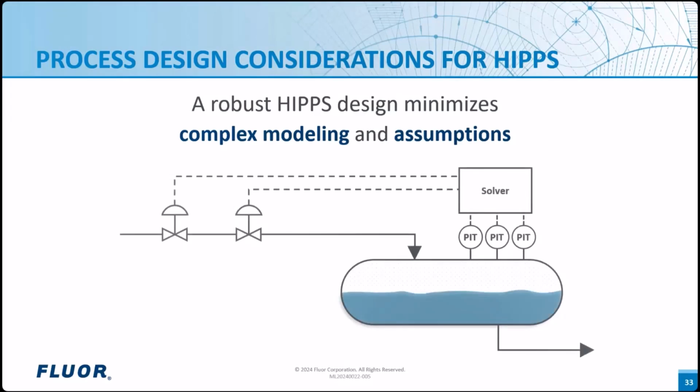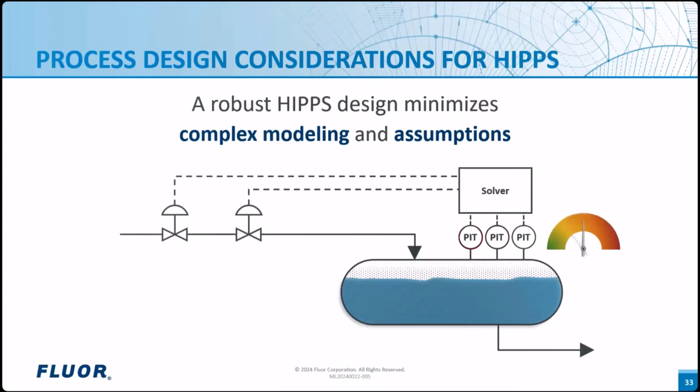This is an example where if liquid overfill occurred, the resulting large liquid relief was impractical to handle. A HIPPS was selected to prevent liquid overfill since there was insufficient time to credit operator intervention. It was proposed that pressure transmitters would provide an indication of liquid overfill. The argument was made that as the liquid rises, the vapor space compresses, and therefore the pressure will be a measure of the impending liquid overfill. It is critical to assess situations where the proposed HIPPS system will not function.